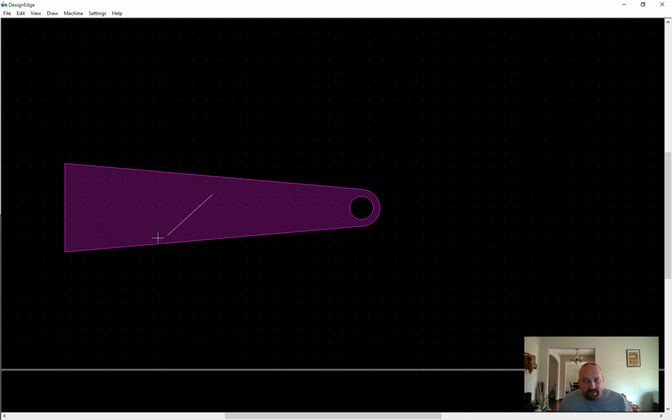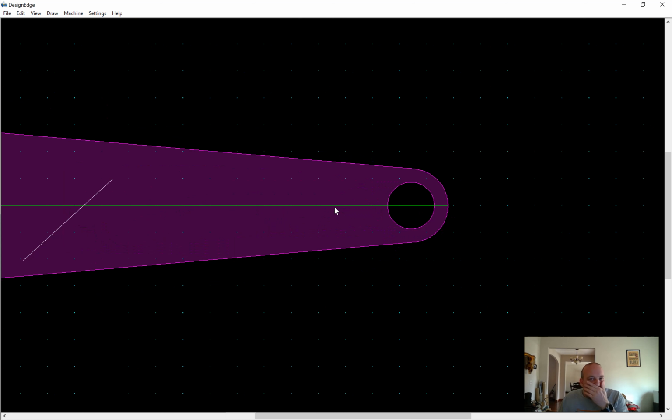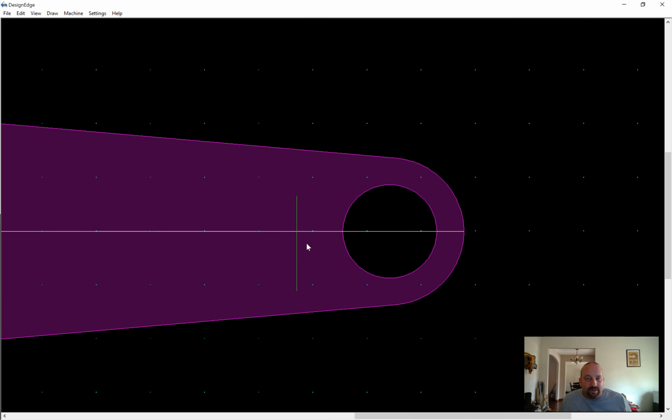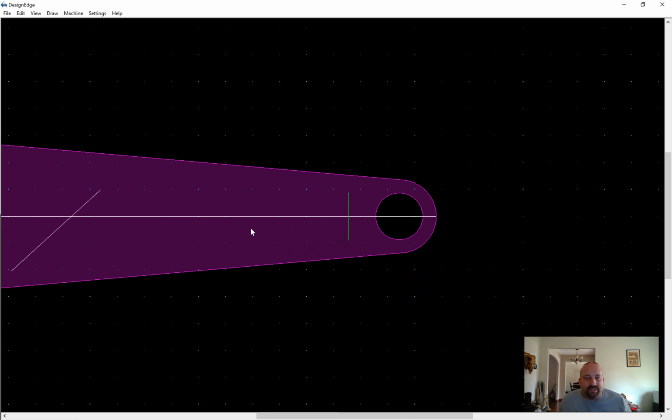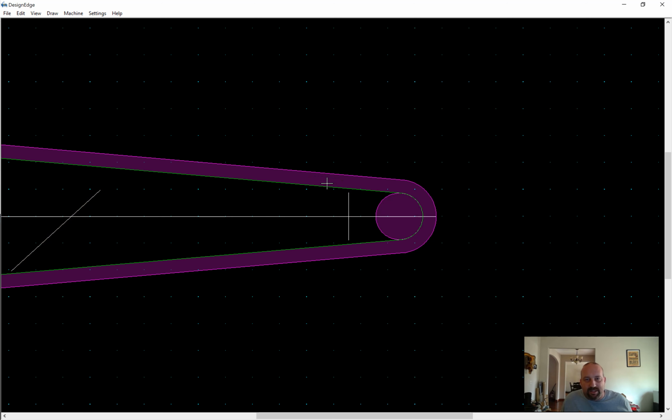So I'm going to put this line from the midpoint to this quadrant again, so it's ortho, and I'm going to now draw myself a line perpendicular to that, because that's the dimension from quadrant to quadrant. Here is the farthest, so M move, M midpoint, Q quadrant, and I'll snap it right there. And then I'll just push O offset, 1 enter, and that'll pop that over an inch to give me an inch spacing. Then I'm going to offset this whole thing in a 1/2 inch, just like was done in the past in the example, and that is again just a reference point.